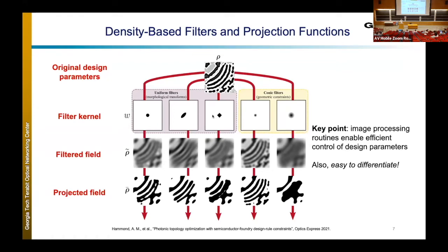Number one is actually a bit unintuitive, we want to filter our design degrees of freedom to help regularize the optimization process. If we just decided to optimize the raw degrees of freedom, we would see a lot of very interesting optimization results that quickly jump into local minima, and it's really hard for the optimizer to jump out of the local minima. But by doing things in this fashion, by first running it through a filter, we actually spread the energy out in the back propagation stage. We spread out our gradient through all the degrees of freedom such that there's a bit of locality in each of our degrees of freedom there. The second reason we want to use filters is because this is a clever way that we can implement minimum feature size constraints, which is absolutely essential when you're designing silicon photonic devices.